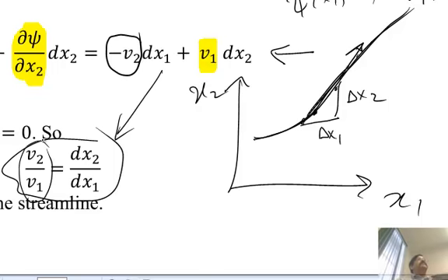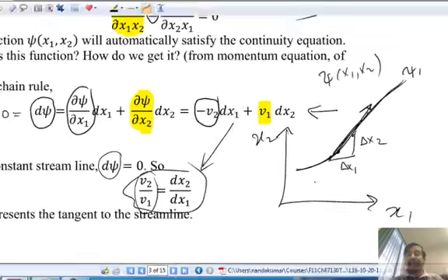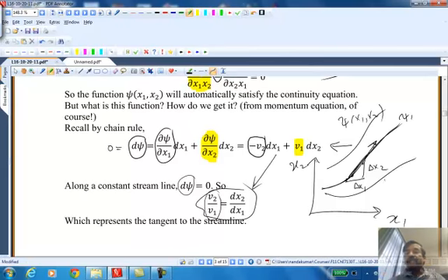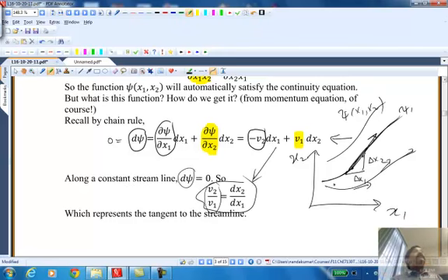So the tangent to the streamline gives you the velocity vector. Okay, so a streamline is a beautiful representation of the flow, because if you have a whole series of streamlines like this, you know the tangent locally gives you the velocity vector. So you know in which way the fluid is flowing. So if I put, for example, a dye to mark how the fluid is flowing, a dye will trace the path of a streamline under steady flow. Okay, so these are all under steady state conditions. Any questions? Now that's a concept. I want to make sure that you guys get it.